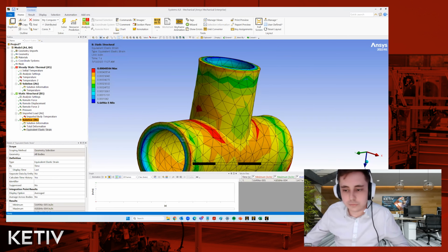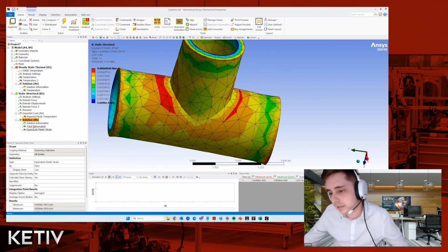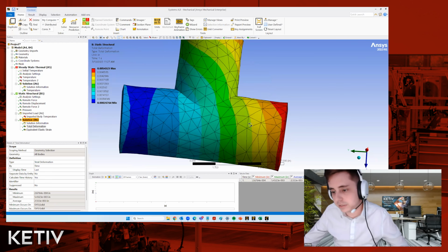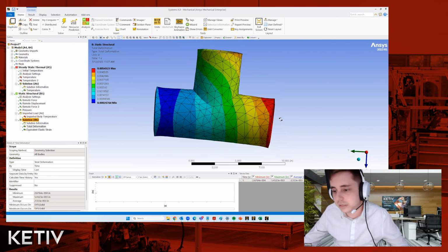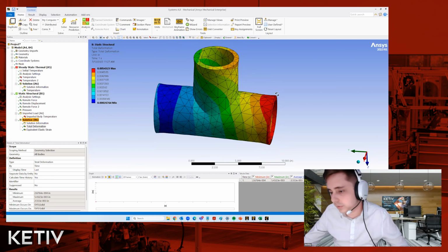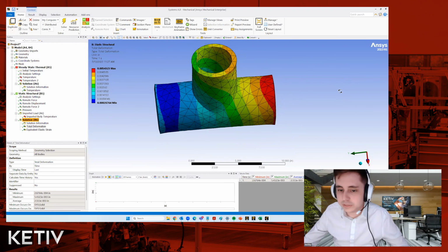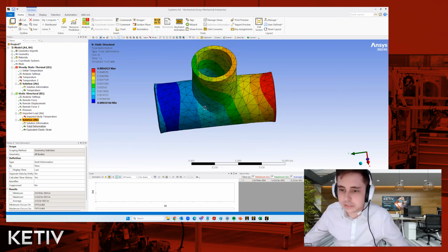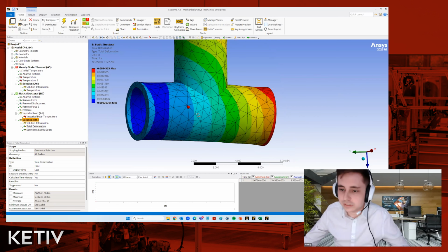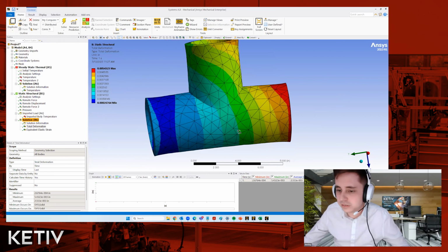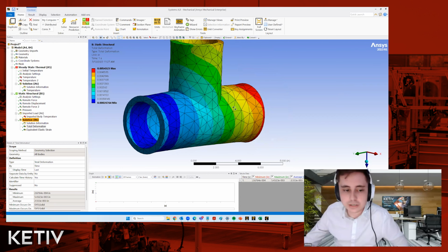And I mean, looking at the deformation, because that's kind of the most intuitive thing to look at, it kind of makes sense, right? Like, this end over here is deflecting downward because we have this pipe assembly that's exerting a load in the downward direction. But there's still, well, there's not a uniform stress around the thing, but there's definitely this entire body is experiencing some kind of load, right?